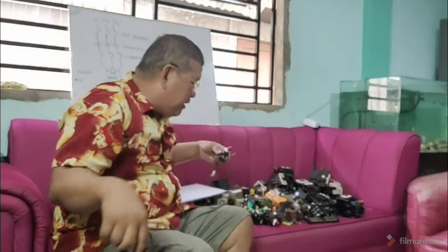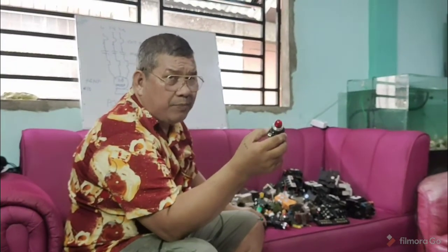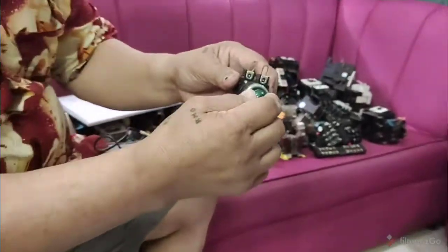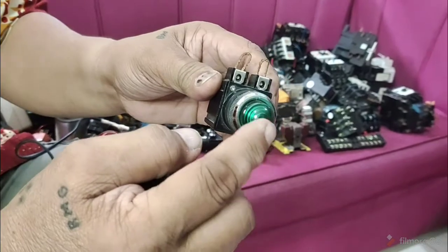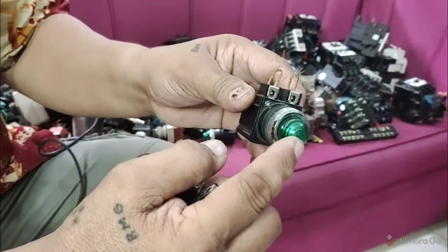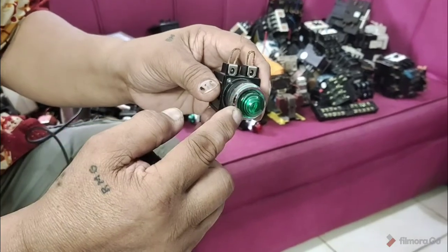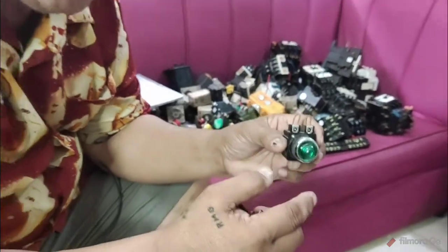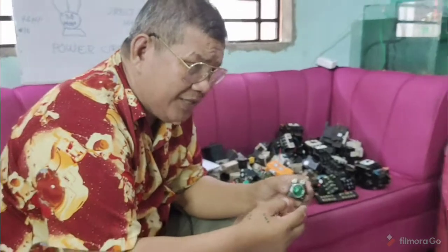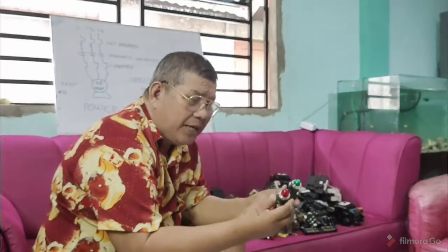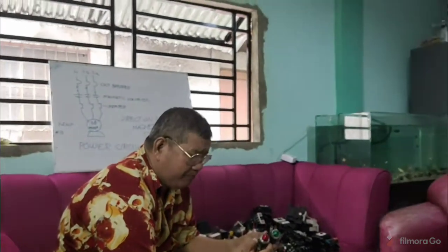No? Then it depends on you. Usually, this is used for a trip lamp or power lamp, while this one is green. So this is the load side, the load indicating lamp. You will connect this directly to the holding coil, where that magnetic contactor is controlling the motor. So you have the green. This is your load. This one can be a trip or can be a power lamp.